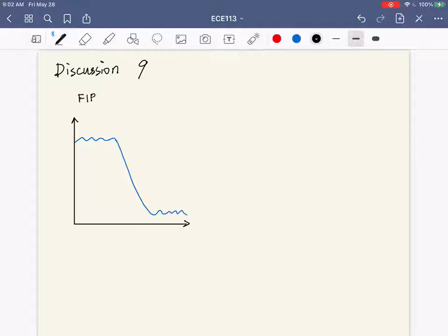So let's first discuss the FIR scenario. For FIR, we usually discuss the H omega itself rather than its square response, okay? And the central point in the passband is normalized to 1, and you fluctuate it within 1 plus delta 1 and 1 minus delta 1, okay? And then if we extend the lower limit, it will match a frequency. And this frequency is called omega p, okay?